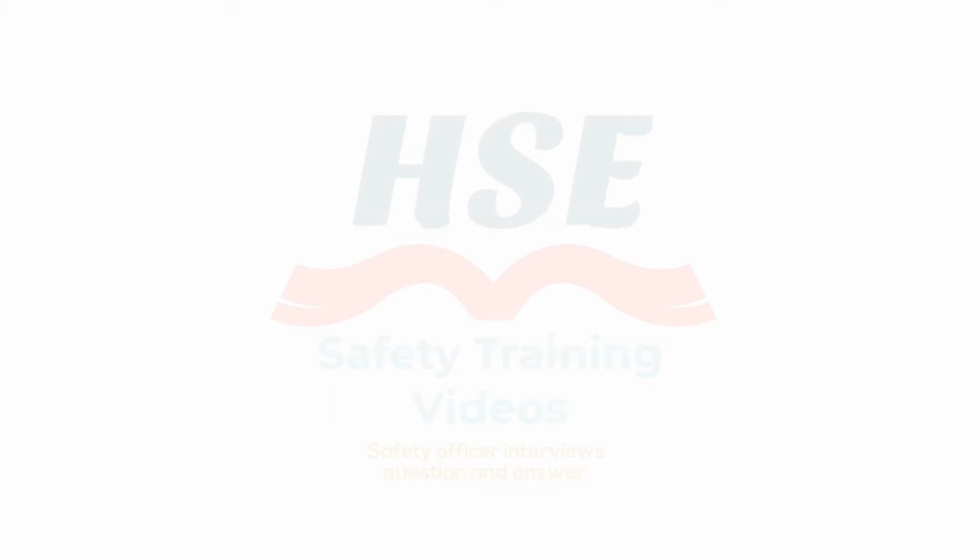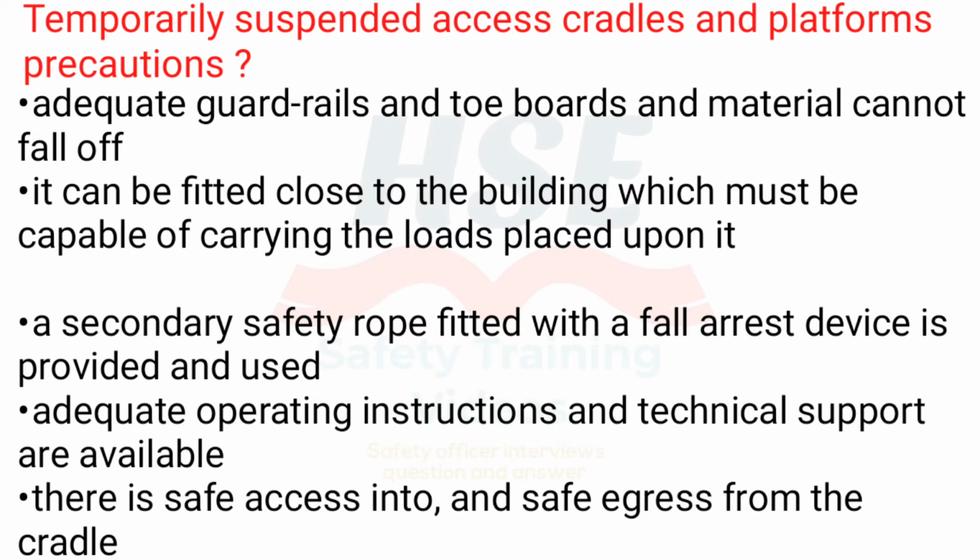Kept clean and tidy. Temporarily suspended access cradles and platforms, precautions: adequate guardrails and toe boards so material cannot fall off. It can be fixed close to the building, which must be capable of carrying the loads placed upon it. A secondary safety rope fitted with a fall arrest device is provided and used. Adequate operating instructions and technical support are available. There is safe access into, and safe egress from, the cradle.